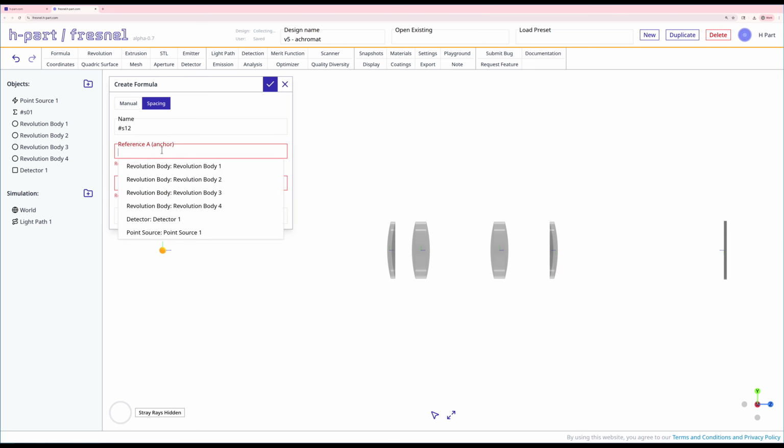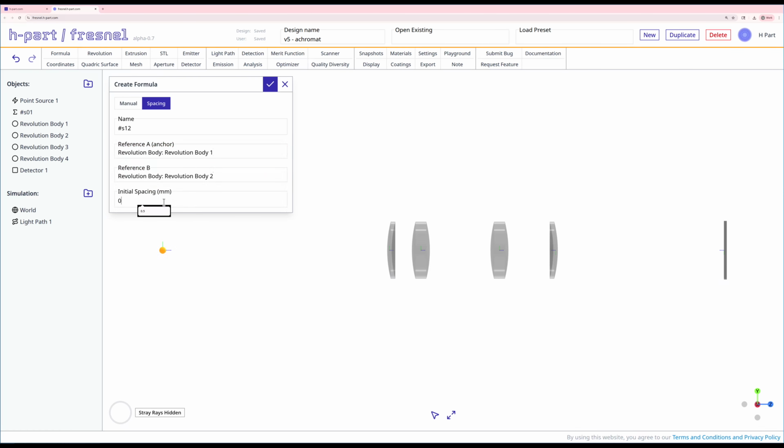And for these UV achromats, because the fused silica has such a low coefficient of thermal expansion, it's a bad idea to cement them. If the lens goes through thermal cycling, the fused silica is just not going to expand at all, whereas the other element might expand quite a bit. That could cause a lot of cyclic stress on the cement, causing it to eventually fail. So we're just going to have an air-spaced achromat to avoid that problem entirely. Put a small amount of spacing there.